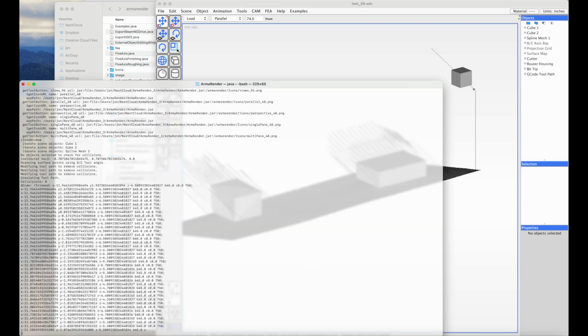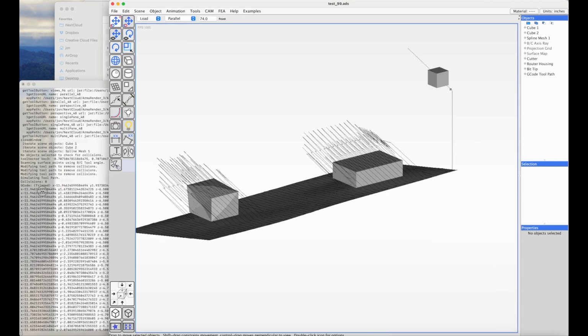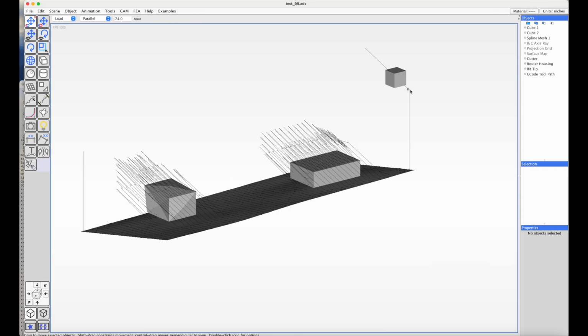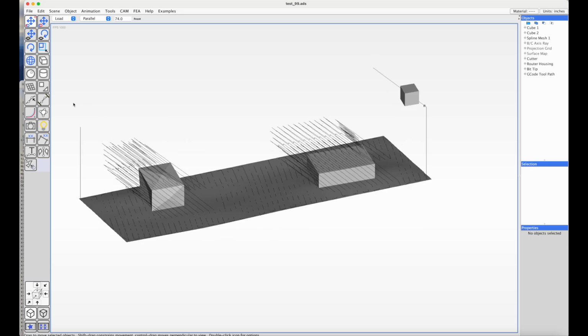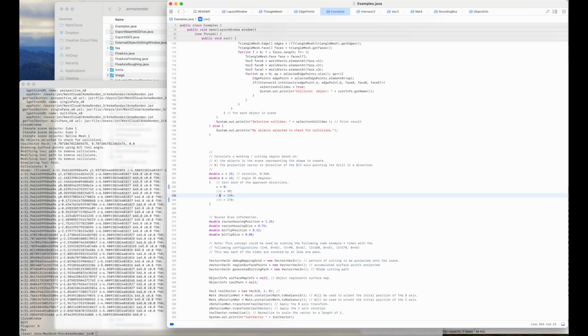When it's done, it's going to print out example G code, which includes the X, Y, Z, B, and C for the direction, and the actual coordinates are not exact because these coordinates are offset by the geometry of the machine, specifically the length between the tooltip and the axis that the B and C rotate, which is just random for the example. I'll do another demo from a different angle.